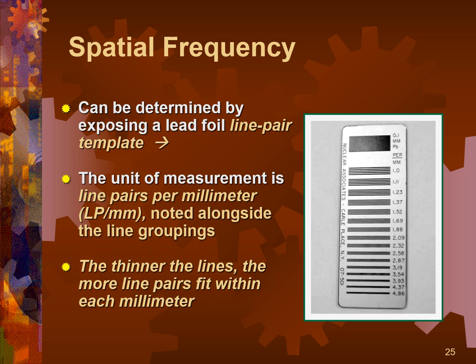So you see the line pairs on your monitor right now. But if you're viewing this on 2K, full screen, I'm going to read it off on mine, and you'll see if your monitor is better than mine in my office. The last one I can clearly see is 1.88. I can see white interspaces in between the black lines. When I get down to 2.09 line pairs per millimeter, it's all smeared together. So that tells me my monitor resolution is roughly 2 line pairs per millimeter.